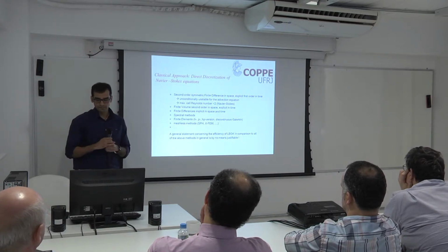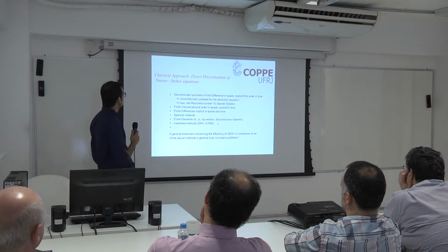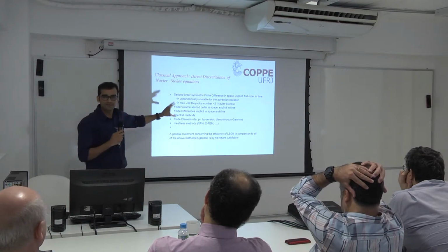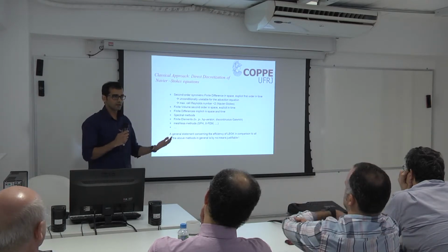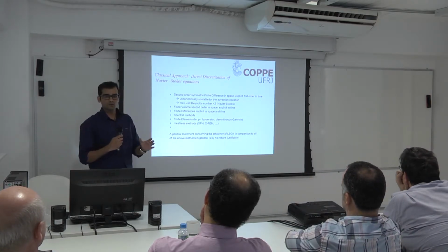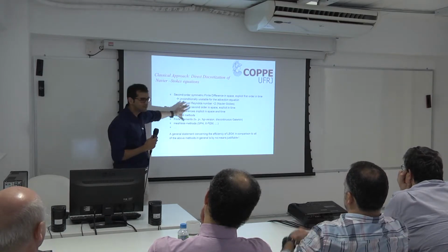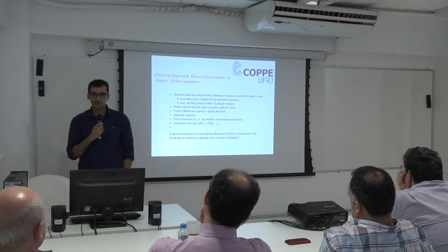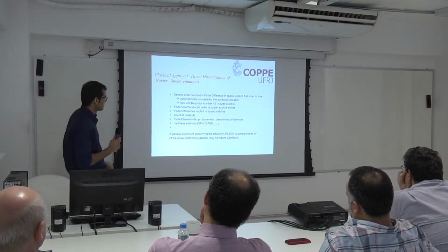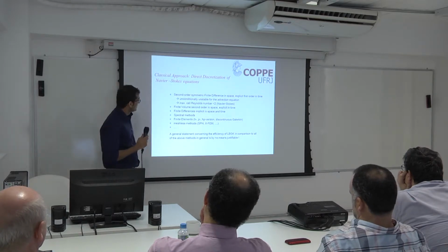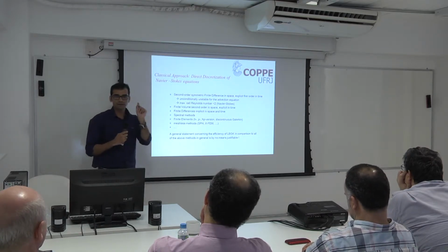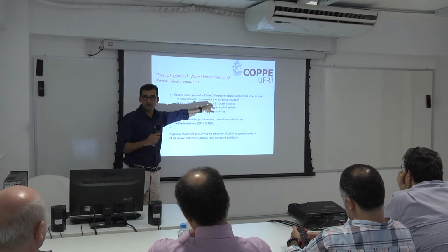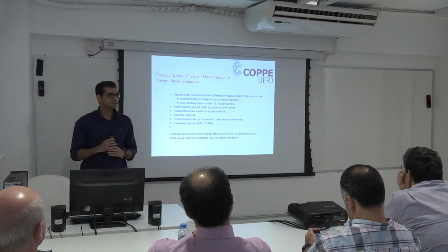So, the classical approach: direct discretization of the Navier-Stokes equation. This is what we do. Scientists generally or conventionally, till today, whoever doesn't want to use Lattice-Boltzmann, do these things. Finite volume, finite element, finite difference methods, spectral methods, these kinds of things they use. But where does the challenge lie? The challenge lies in the maximum cell Reynolds number for Navier-Stokes. You know?